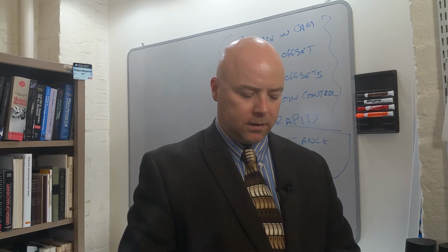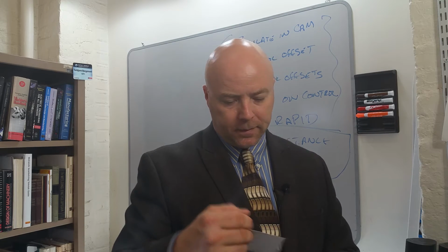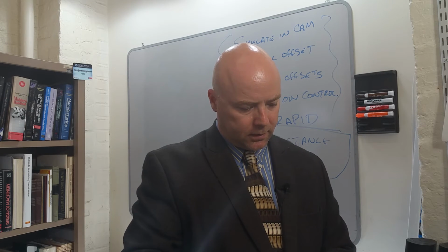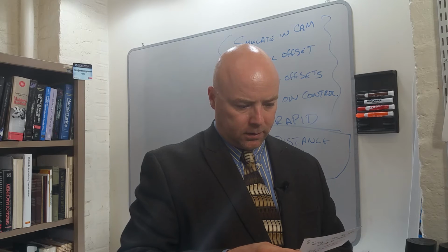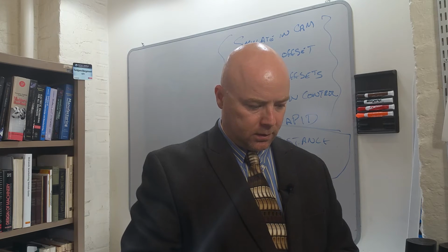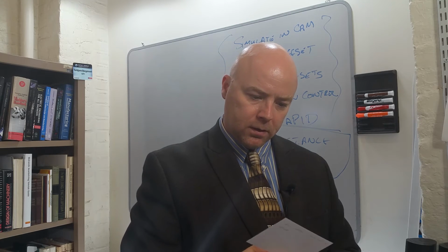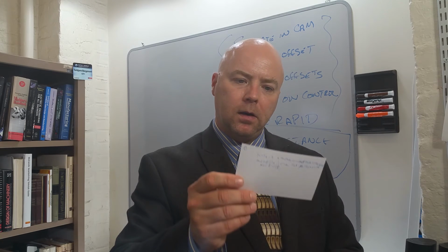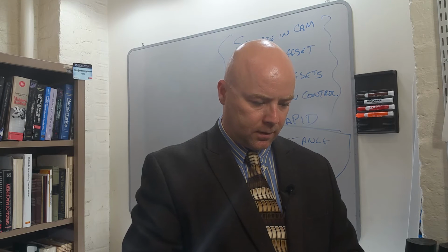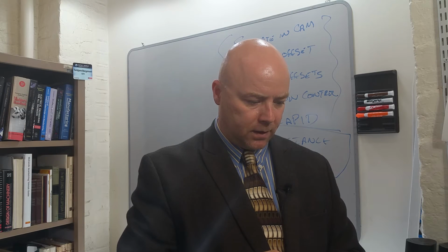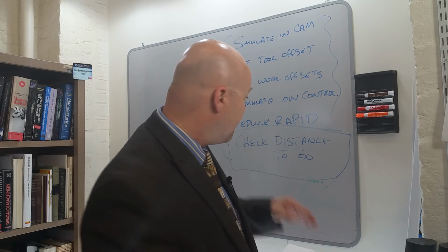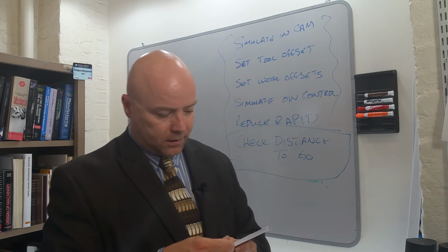Most important is simulating. Simulate. Most important check is the operator. Simulate. Based on what I've seen, the offsets seem fairly important. Well, you can't do it without the offsets, but if you've screwed up the offsets, you'll catch it with check distance to go.